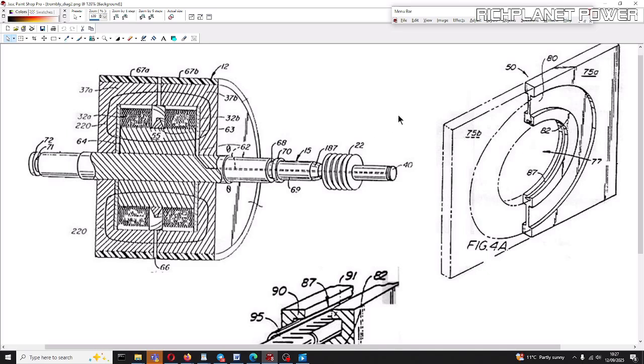So just to go through the functioning of it, we've got a shaft rotating at 7,200 RPM, and fixed on it is a steel disc. Now this is more of a cylinder shape than a disc or a drum shape, but that's your rotating disc there, which is inside here. Now on it, this is a contact, so that's where it's going to make contact with this thing here. Now we'll notice that there's material all the way around here. This is iron, and this all rotates together.